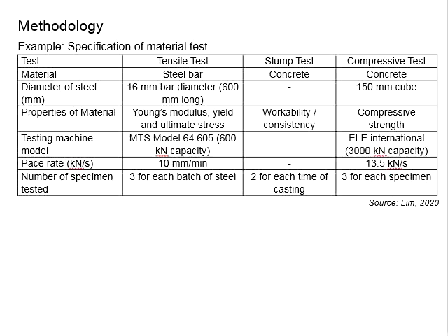Normally for concrete with aggregate greater than 20 mm, when you want to produce the samples, it should be either a cube or cylinder of size 150. Although you can use a smaller size, it is generally understood that a 150 mm diameter cylinder and a 150 mm cube will give you more representative data.